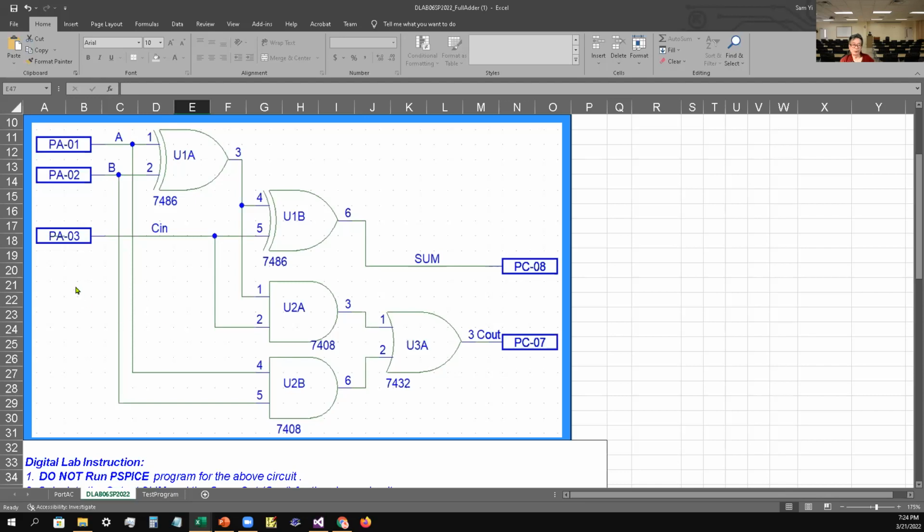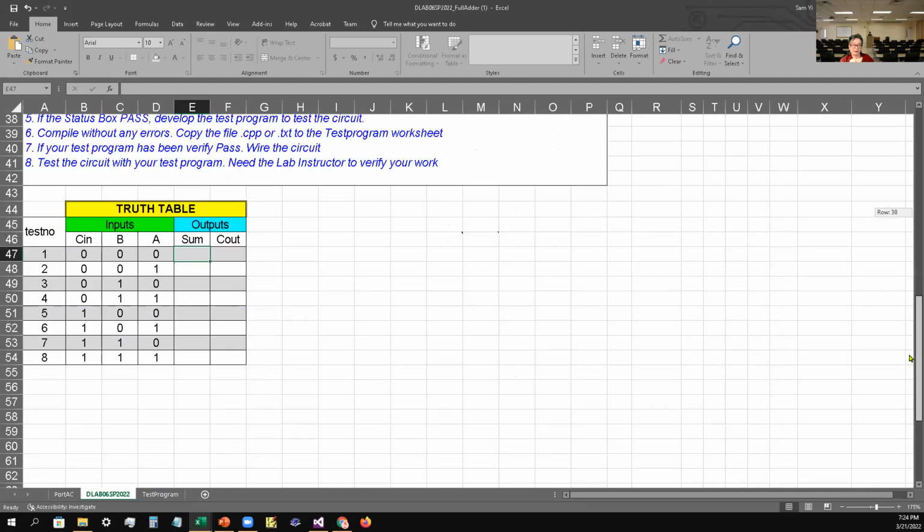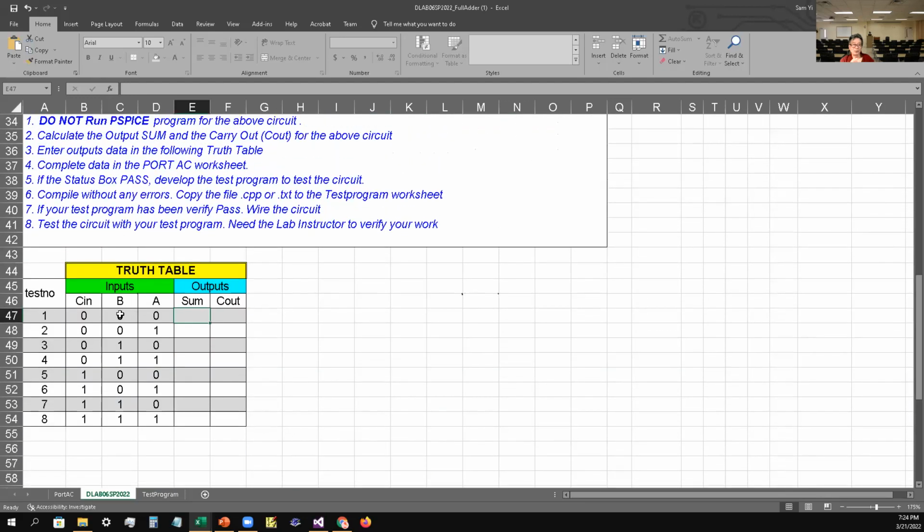So now you can move up to the truth table. In the truth table, you get A added to B. However, you also have to add whatever carry to the next column. That's what they call a carry in. So 0 plus 0, you get a sum of 0. And a sum of 0 doesn't have any carry, so the carry out would be just 0.